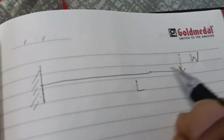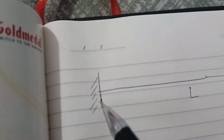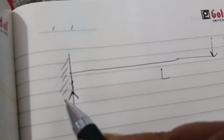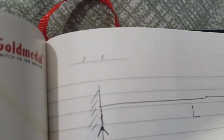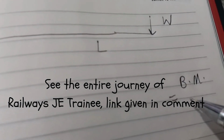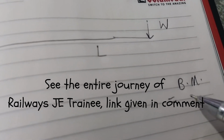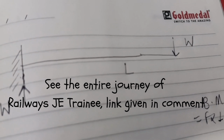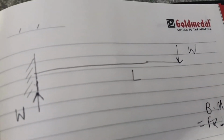This entire W will be coming at this support. So the reaction, the counter load, becomes the reaction, and that is nothing but W. This entire load will be taken by this support. So the reaction that is coming at the support is nothing but again W. And we know bending moment is the moment of force. Moment of force is force into perpendicular distance, or the arm through which the force acts.